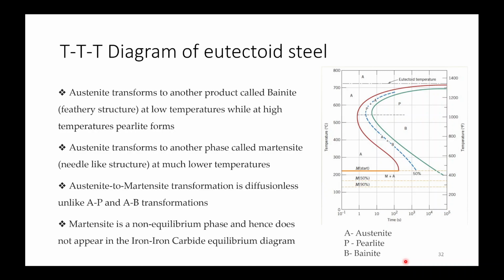Yeah, so Hume-Rothery rules have four rules. If the difference in atomic size is higher, and if there is more electronegativity difference, those things will define whether the overall energy is reducing or becoming higher. So it will depend on that. It shouldn't change your structure much. If, in the case of a nickel matrix, you are substituting copper atoms, then there will be a completely substitutional solution, complete solid solubility.